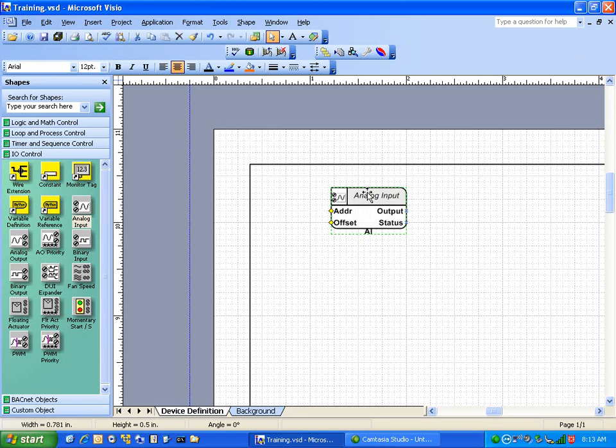So as we learn this object, one of the things I see some of the guys doing is they pull an object, and like in the LAN world, it really wasn't important to give it a name. Some people like to give it a name, some people don't like to give it a name, some people are in a hurry, some people aren't. But in the BACnet world, the names are very, very important because we learn this object up in a UNC. So it's important to identify it as it is.